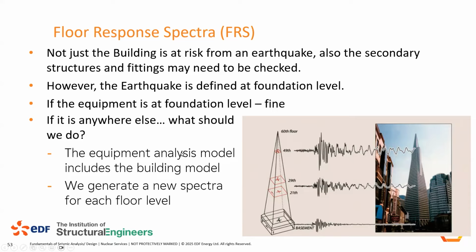One is you use the base input, so you use the foundation input, but you ask your equipment designer to actually model the building. So they can use that input as long as they model everything between that level and their equipment. Although they're trying to design a bit of equipment, they're also having to model and analyze all the building structure as well. So you can ask them to do that. They will tell you to go away, maybe less politely, and they wouldn't do it. And I'm not sure that many of them would have the capability to do it anyway.